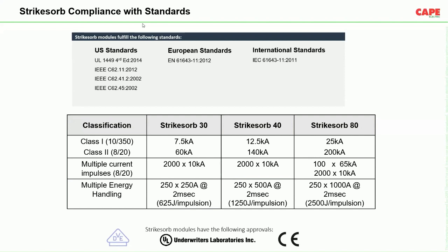multiple high energy handling. See, the lightning also consists of a long duration stroke. So there are positive strike, negative strike, subsequent strike, and a long duration stroke. Long duration stroke is a small current but flowing for a longer duration. These SPDs are also tested for that particular purpose. You can see on the strikes, 250 shots, 250 amps, 2 milliseconds. 250 times these SPDs are tested.